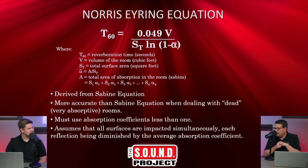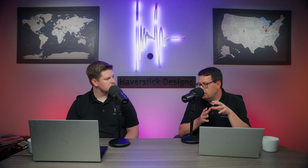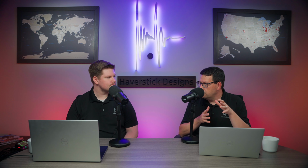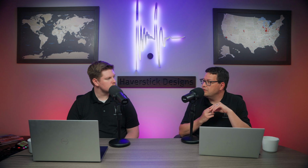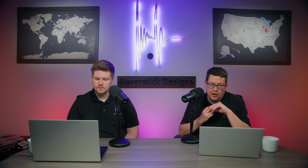And the reason we have to use an absorption coefficient below 1 is because you can't take a natural log of a negative number. And so if you put in a number there that was greater than 1, then you would end up breaking the equation and it wouldn't work anymore. But the difference with this one is it assumes all those surfaces are impacted simultaneously rather than one after another, and also each reflection being diminished by the average absorption coefficient. And I will say that this one, like I said, we don't use it as much as we do other equations, and so we don't have as much experience using it. But when it warrants itself, it is still very accurate, and something that is helpful in those extreme cases.